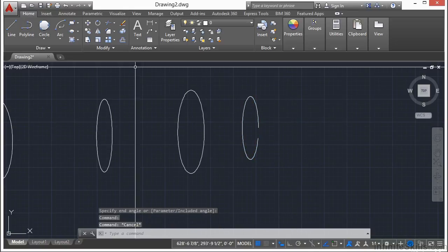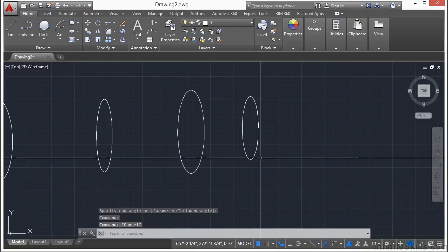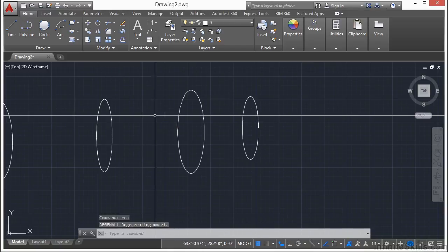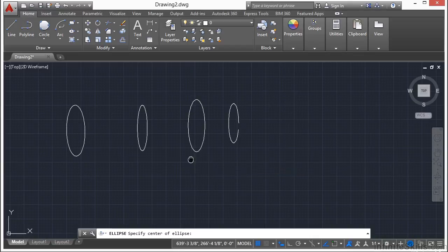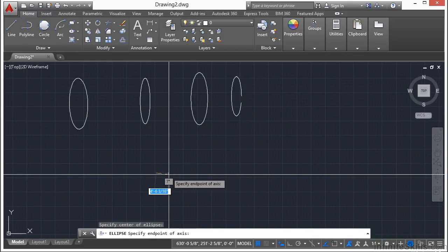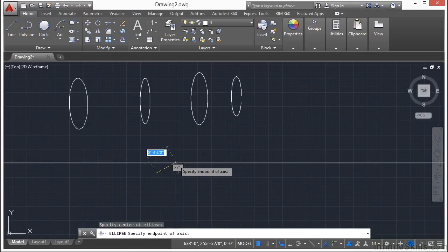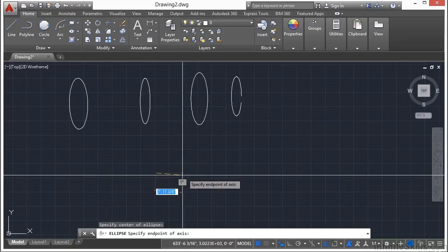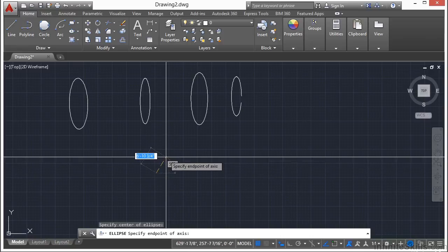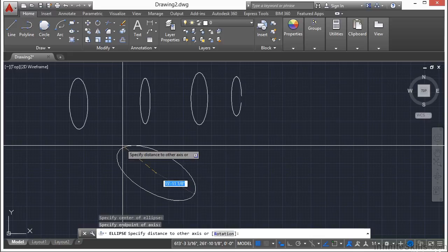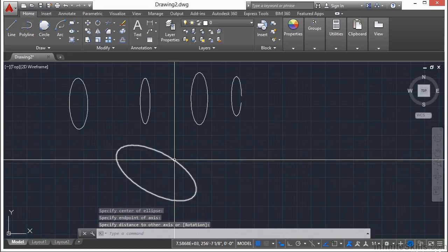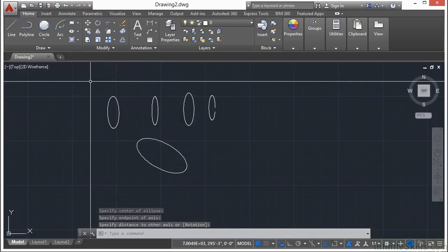Now the ellipse, keep in mind, if your ortho command is turned off, like I have mine off right now, when I pick my center point, and then I pick my width, it's going to be drawn at this angle. It's not perfectly horizontal or vertical. So it can be oblong like that. So there are a lot of different ways to draw it. And it depends, again, on exactly what you're trying to draw, the perspective of it, or what information that you have at the time.